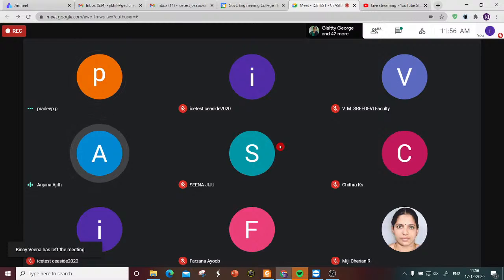Similarly, how can you mix 2% of steel fibers? I tried up to 2%, but it was a very harsh mix, but 1% gave the best result.